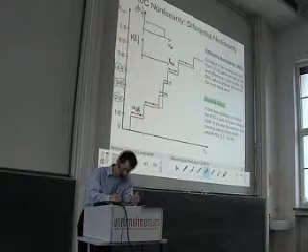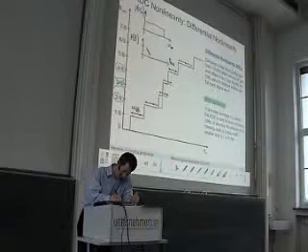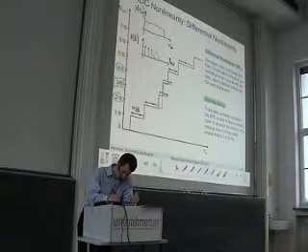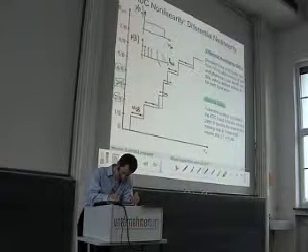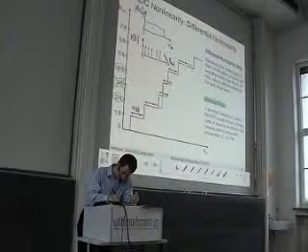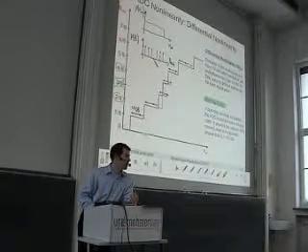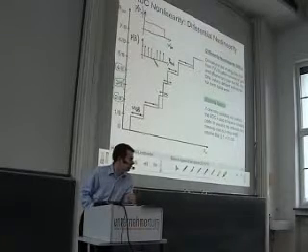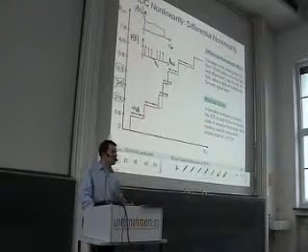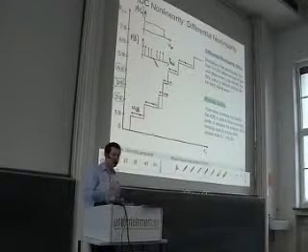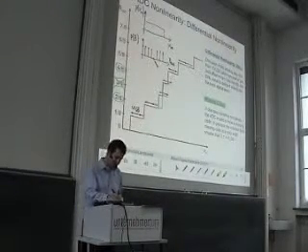So you should get something like this. Same probability for each value. However, if one value is missing completely, or is very, very small, then this is an indication for this missing code. So this is a so-called histogram test.